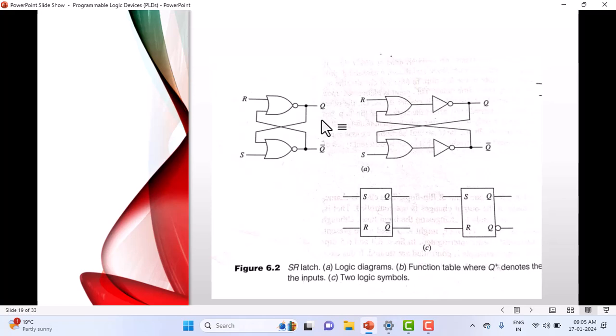Okay, that's the state we are observing here. And look at other combinations also. What will happen if I change the inputs? Here I started with 0 and 0. What happens if I assume 0 and 1? This state definitely remains as it is. Now see here, let us start with the first bottom one. I have taken 1 here, 1 and 1. It is 0, 0 goes here, 0 and 0. It is 1, 1 comes here, and then again 1 and 1 remains 0. That means this remains as 1, that is the next state, and this remains as 0. This is called set state.